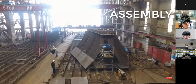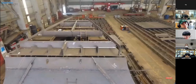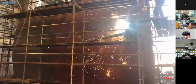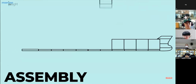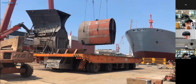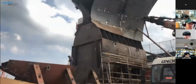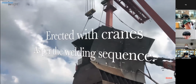Assembly. Once the plates and frames are prepared and given the required shape, they are welded according to the structural drawings prepared by the design department of the shipyard. The hull is divided longitudinally into blocks, and each block is again divided into assemblies and sub-assemblies. During the shipbuilding process, each ship block is brought to the building dock, where they are erected with cranes as per the welding sequence. After each erection, welding is carried out on block joints.